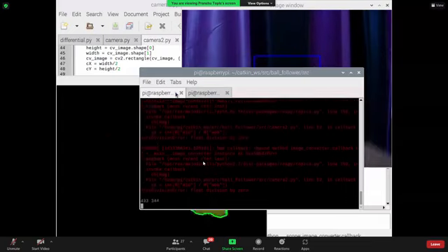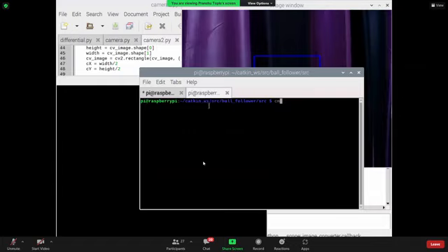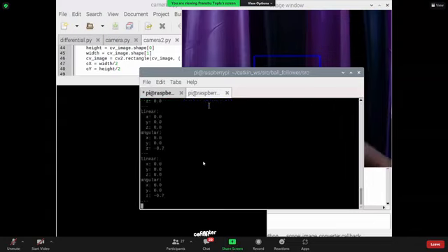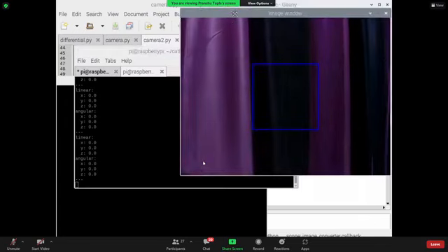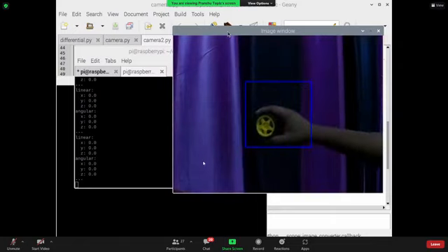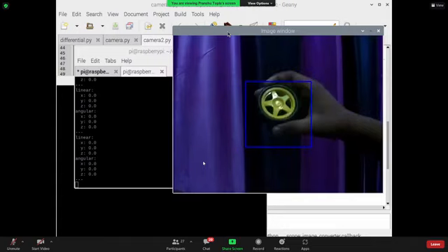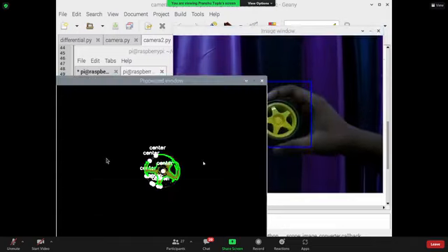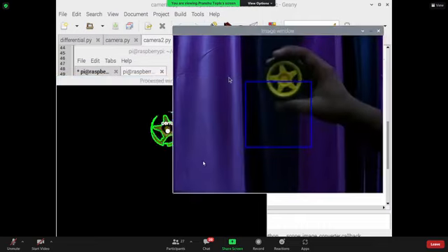Whenever we don't get an error, we are getting the center point. So now let's echo the command velocity topic. So we'll do ROS topic echo /cmd_vel. What it will do is print what velocity is going. So right now you can see it is 0. But I will show you the camera as well and the ball. Yeah. So whenever my ball is in the center, whenever it is getting detected, why is it hanged?